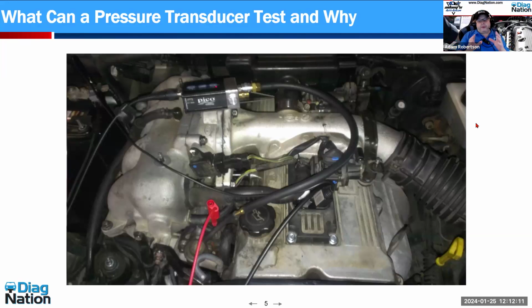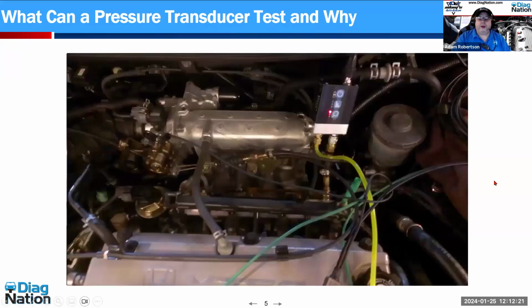Thank you. But at any rate, guys, I can actually see each injector open and deliver fuel and vibrate that. That's another place I use pressure transducers. Well, you're like, well, Adam, that looks very Honda-ish. It's a Honda. But what I have here is I have now hooked my absolute, there's that word again, which we'll get to, pressure transducer hydraulically to the fuel rail.